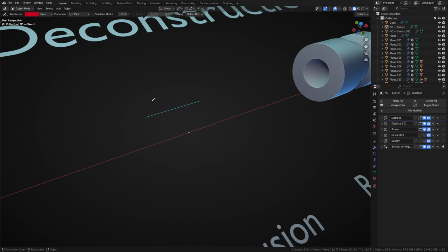We can still go further. Let's take one vertex of this edge and unextrude it towards the other, leaving us with just one vertex. Since a vertex is the smallest, most straightforward form of geometry we can create in Blender, this is as far as we can go.